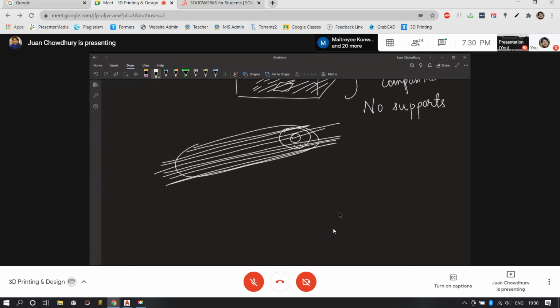So if you know that there's something called a spherical joint, okay? There's a cup in which there's a ball, and this ball is connected to one shaft. This cup is connected to another shaft. That's a sphere within a hollow sphere, okay? These sorts of assemblies can be directly made because these are permanent assemblies. You cannot make them unless you have fabricated over them. Okay, it's not possible otherwise. So these sorts of assemblies can be right away made in an SLS sort of machine.